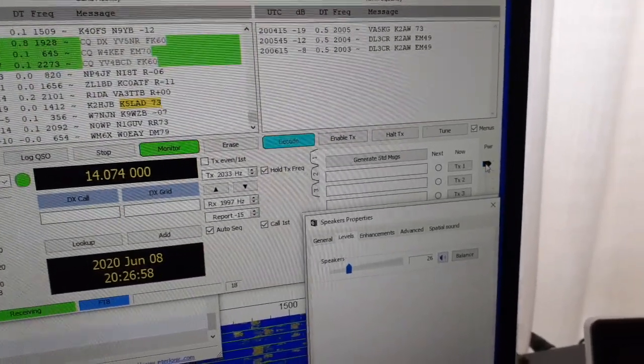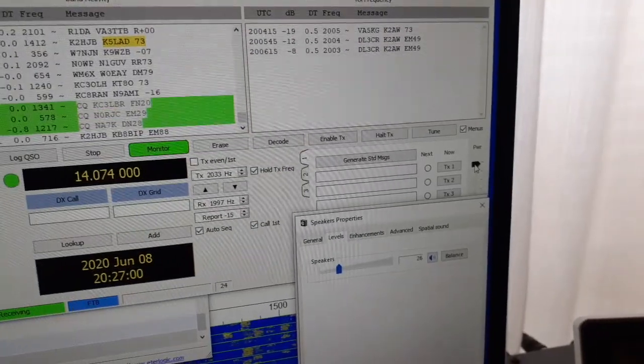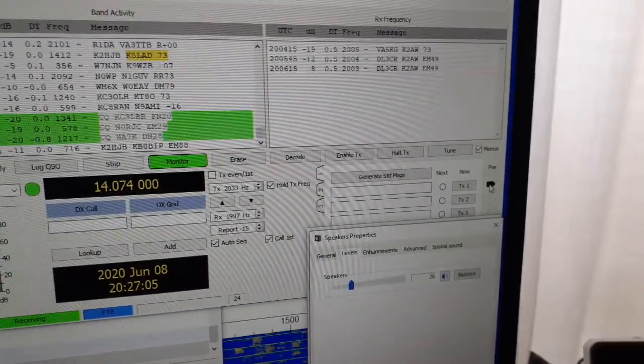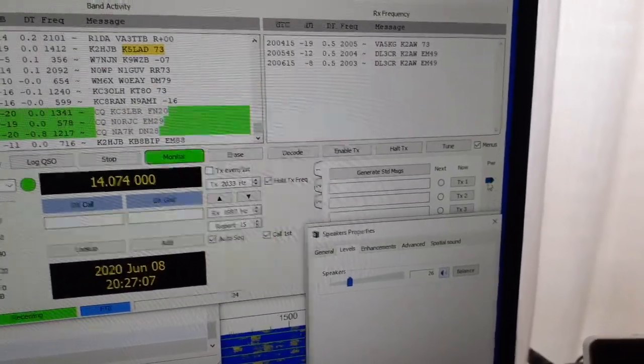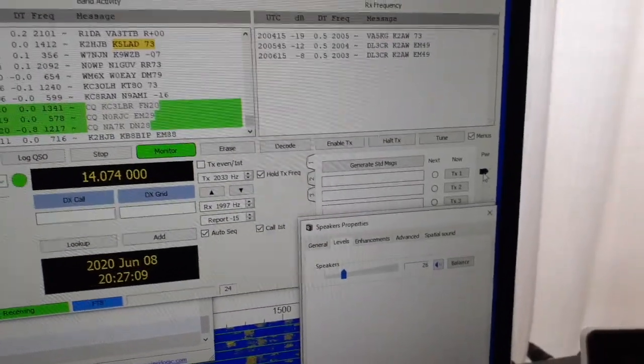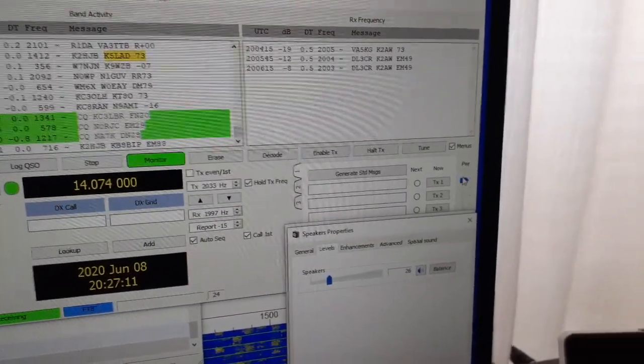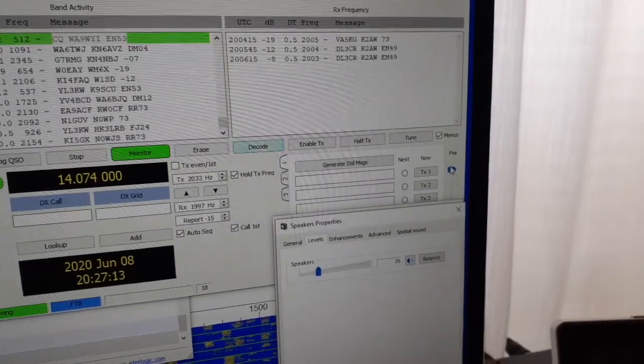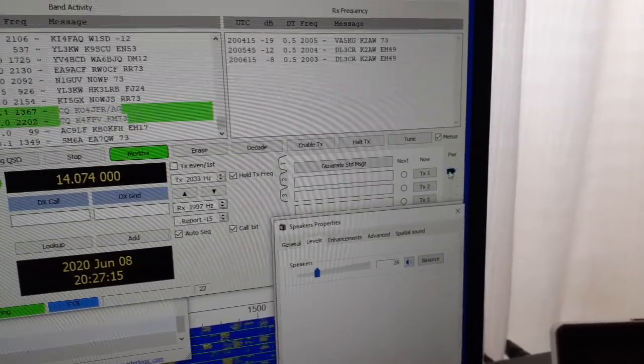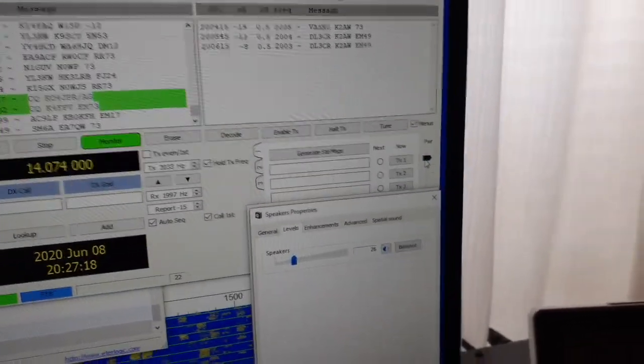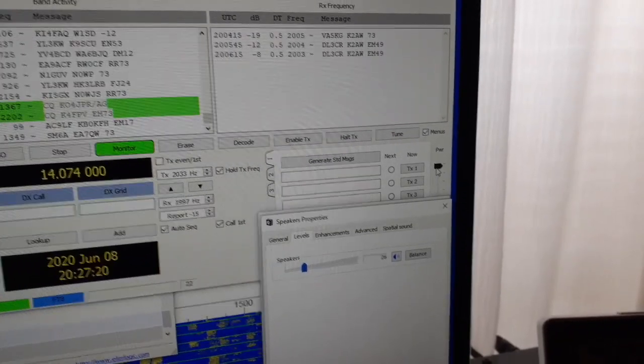Mine's almost all the way up. I believe it's about 1.1 dB down. That's the unit of measurement here. So it's not quite all the way up, but it's close. If I turn it all the way up, I might see one bar of ALC on the radio, usually under transmit. So I just knock it down slightly just so that ALC action disappears.